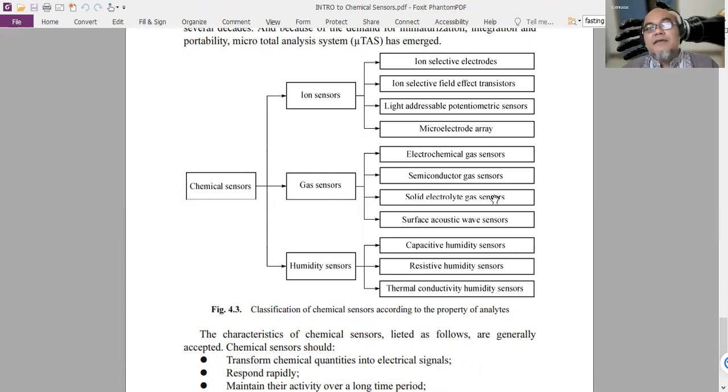So you see here that chemical sensors are very much related to the material properties, as well as the related physical-chemical or chemical-physical principle being used. Many of these chemical sensors are based on the selective filtering of the chemicals, and from there they are transduced into a physical transducer, either using an electrode or transistor, potentiometric or radiation sensor, light, etc. While some others depend on the electrochemical reaction between the analyte and the material of the chemical sensor.